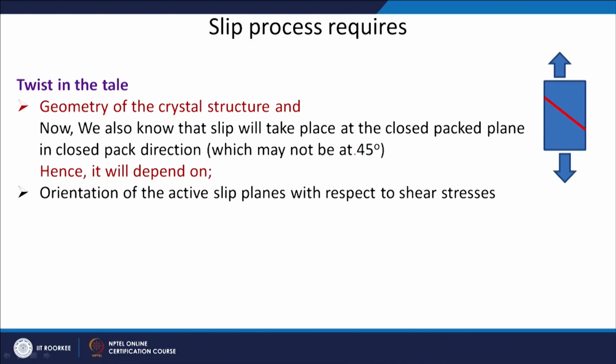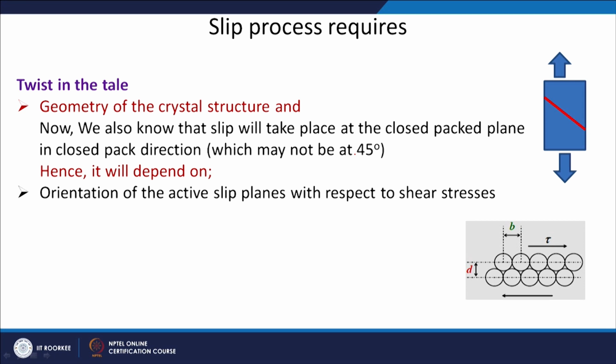Hence, it will depend on the orientation of the active slip planes with respect to shear stresses. Basically, the atomic arrangement is what decides whether you get deformation or slip in that particular direction or not.